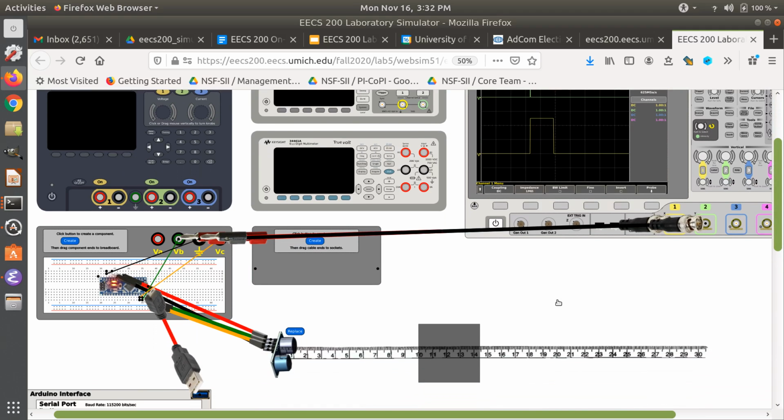So let's just test that out. If we drag this obstruction to say 15 instead of 10, it should get much wider. Drag it to 20, it'll get even wider. And so the students measure that pulse width and convert it into distance to see if they think they understand how that pulse width is converted into distance.